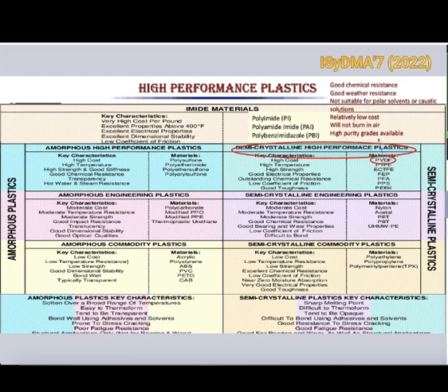As I pointed out, we use different high performance plastics, and PVDF is one of them, as you see in this slide. One of the semi-crystalline characteristics of PVDF is that it has good chemical and weather resistance and displays good resistance to distortion and creep at low and high temperature. Although the chemical resistance is good, the polymer can be attacked by very polar solvents, primarily amines and concentrated acid. So PVDF has limited use as an insulator because of its dielectric properties. But the polymer is important because of its relatively low cost compared to the other fluorinated polymers.